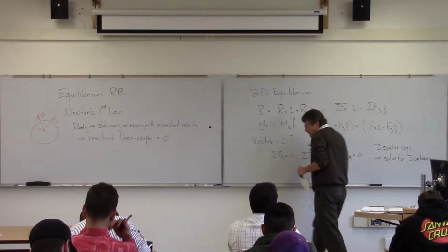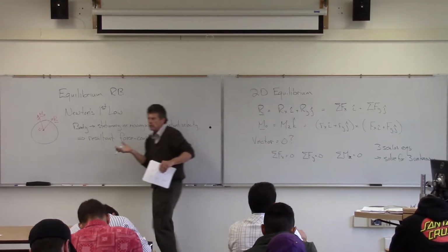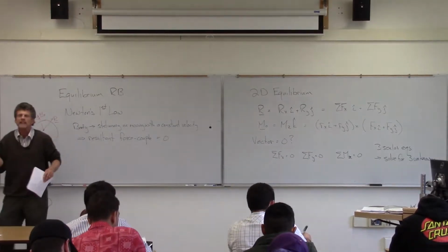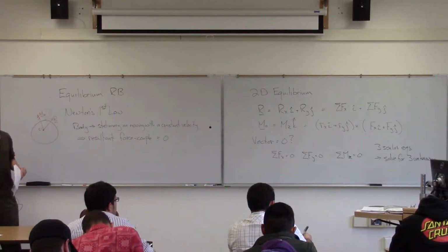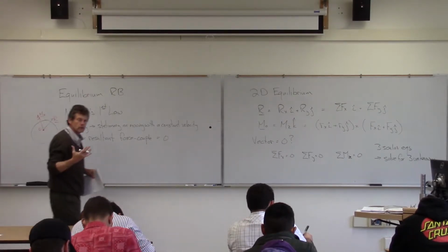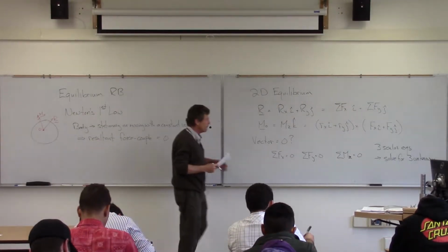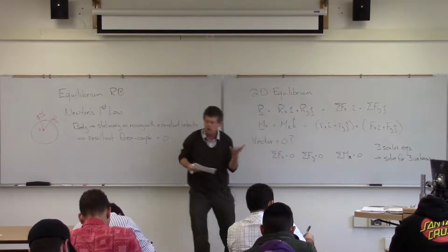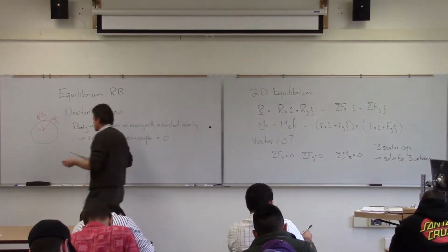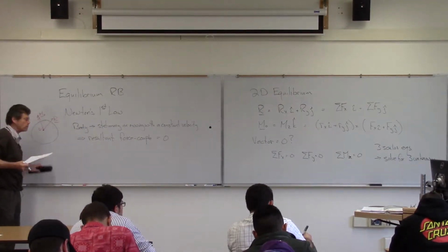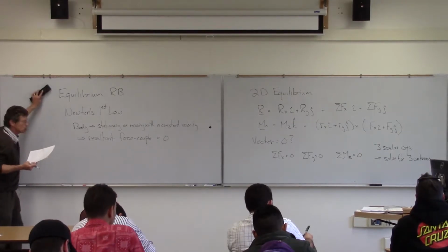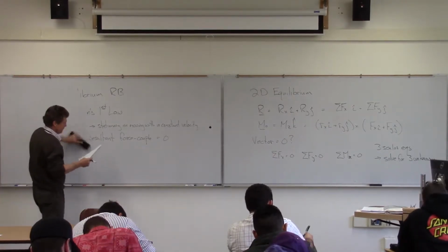And since we're setting that right-hand side equal to 0, that means I can solve for something on the inside. Some x component, some y component, or some z component. And I can solve for those, and then find an unknown force acting from a support or some cable attached to it or other body.